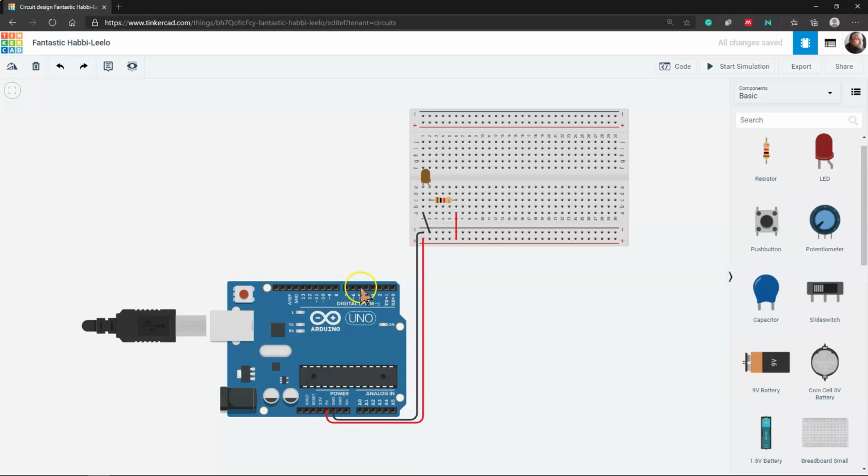for the digital pins. Now, some of these are marked where you see TX, RX. You get things that have the tilde and stuff like that. And right now, we don't have to worry about this too much. I would stay away from using the pins 1 and 0 for right now and just go from 2 to 13. And we'll learn later what this little tilde means. But as far as you're concerned, we can pick any one of these pins. So right now, as we're wiring stuff up, I want to pick one of them being digital. And I know in the future, I'm going to plan, okay, I want to use this so I can control it as an output.